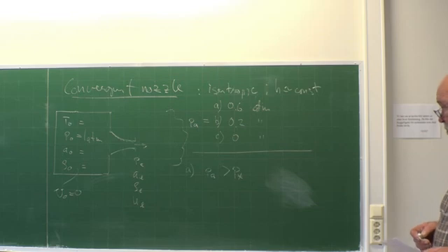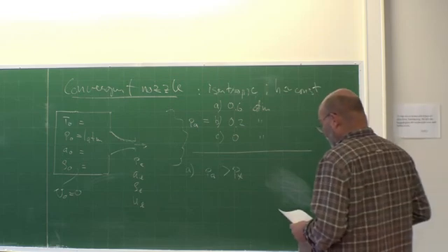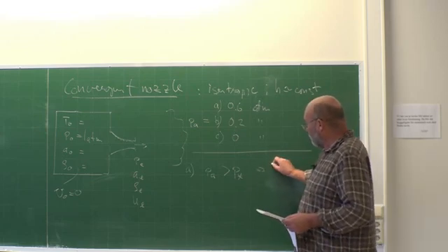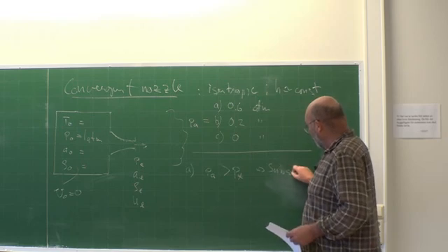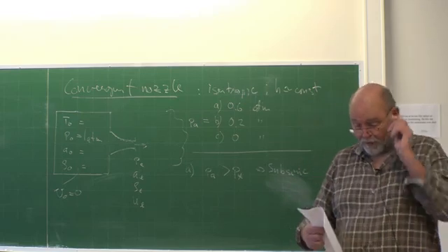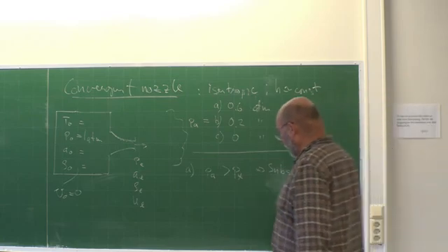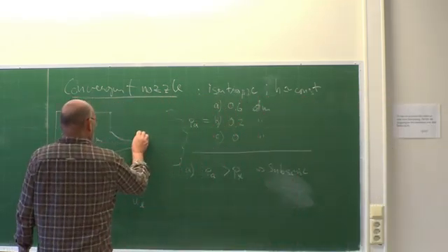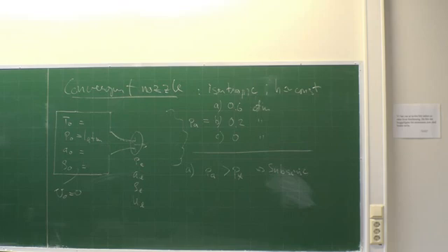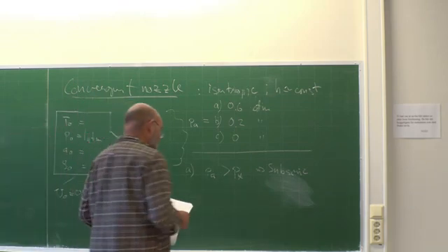No, we don't get a sonic or a supersonic flow. We will have a subsonic situation. And yes, you can find whatever you want from these isentropic relations. What's the solution in this narrow opening? You will find a Mach number of 0.8 something, and everything should then be good to go. We have the solution for everything there.